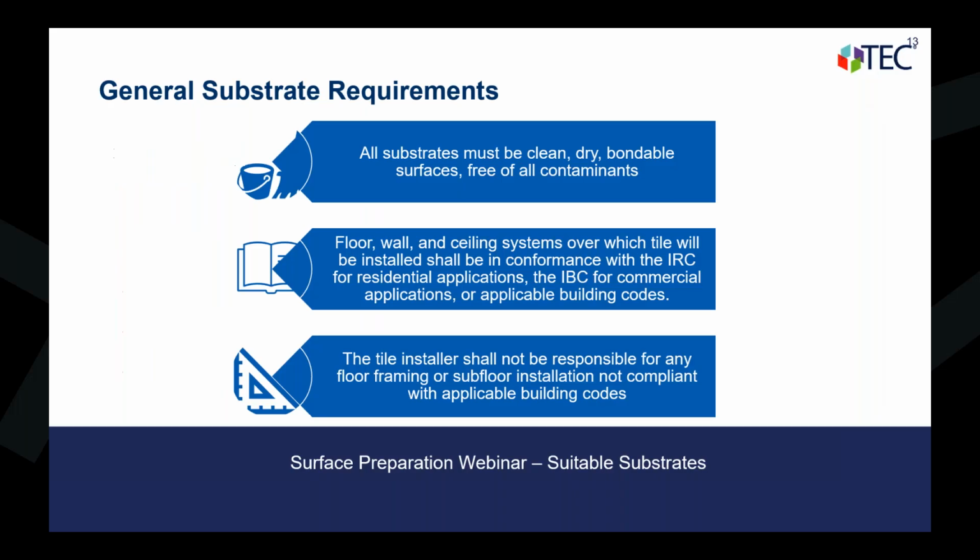Again, going back over some of the requirements for all substrates, they need to be clean, dry, bondable, free of all contaminants, and meeting any of the IRC or IBC building codes that we need to have there. One thing you want to definitely look at is if there's any wood floors. As an installer, we don't want the installer to take ownership of a poor framed floor and have to assume that liability.